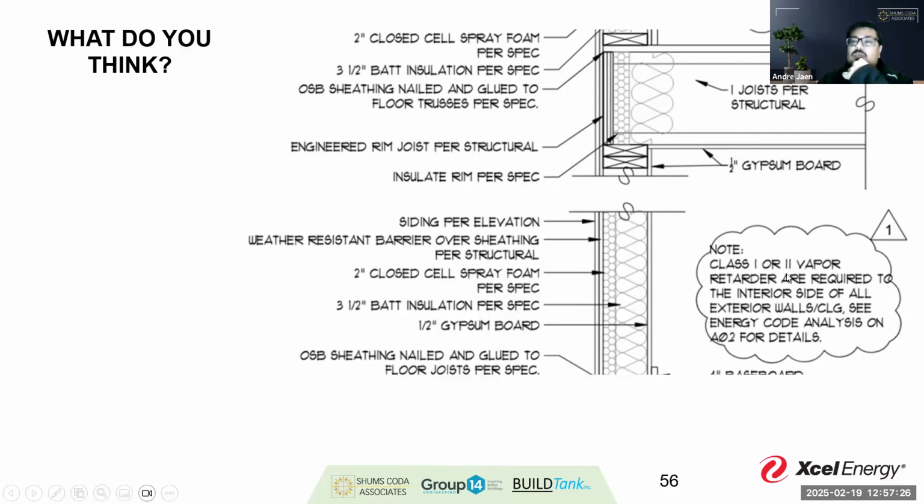And now we have class 1 or class 2 vapor retardant. Well, which one? I mean, that's a significant difference there. One's kraft facing and one is potentially a problem, right? Potentially a hazard. And this is exactly why that matters.